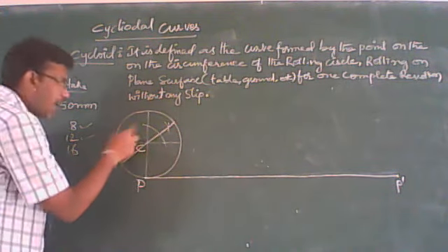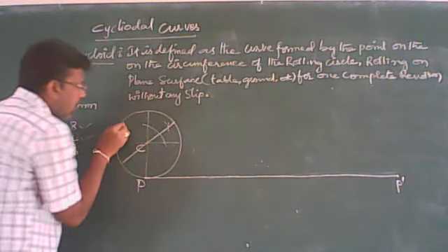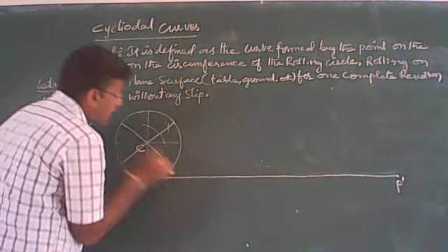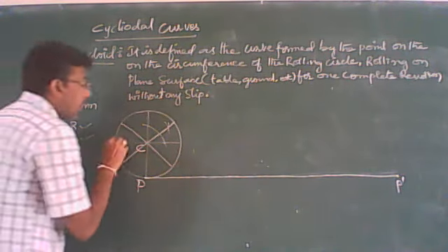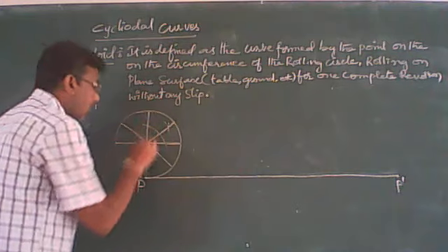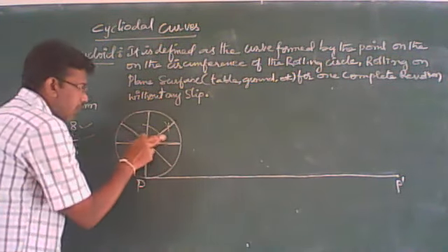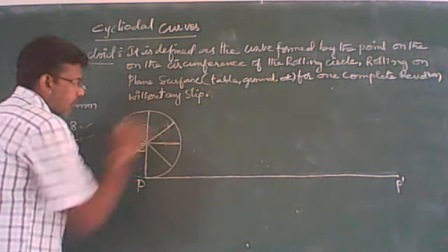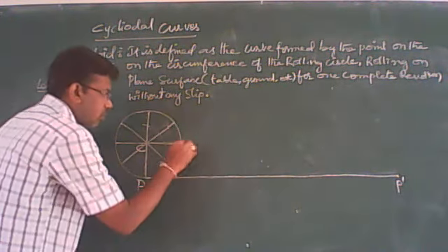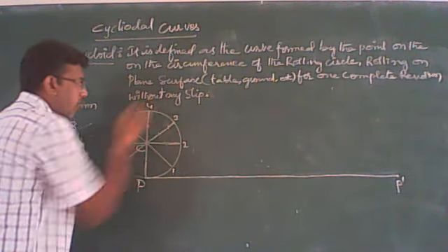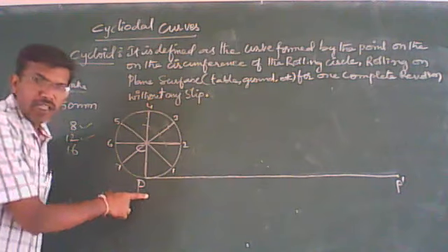You need not make another angle bisector. Simply draw a line perpendicular to this one, passing through the center of the circle, and the circle is divided into 8 equal parts. Now we can see clearly it is 8 equal parts. Okay, so now I'll erase this one. Fine. Now I will name these as 1, 2, 3, 4, 5, 6, 7, and the 8th point is P.